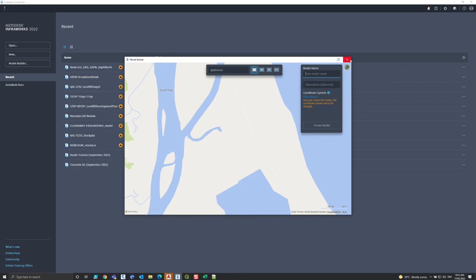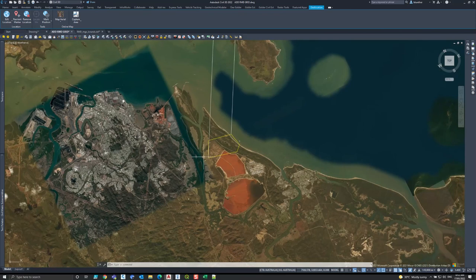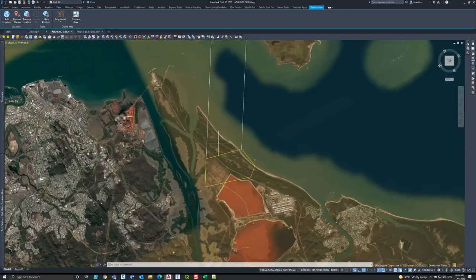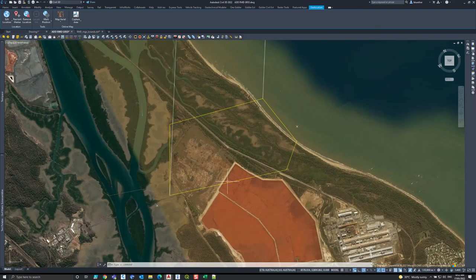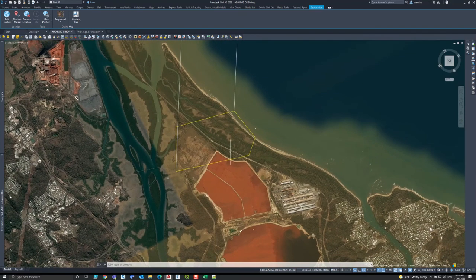So quite often local grids like that can cause you a lot of pain. And this little workflow can really help you manage data, particularly older sites that have lots of historic data in local coordinate systems. But these days, people are still using local coordinate systems, usually due to some sort of software limitation with some sort of mining software or something like that. And this little workflow can get you out of trouble. Enjoy.